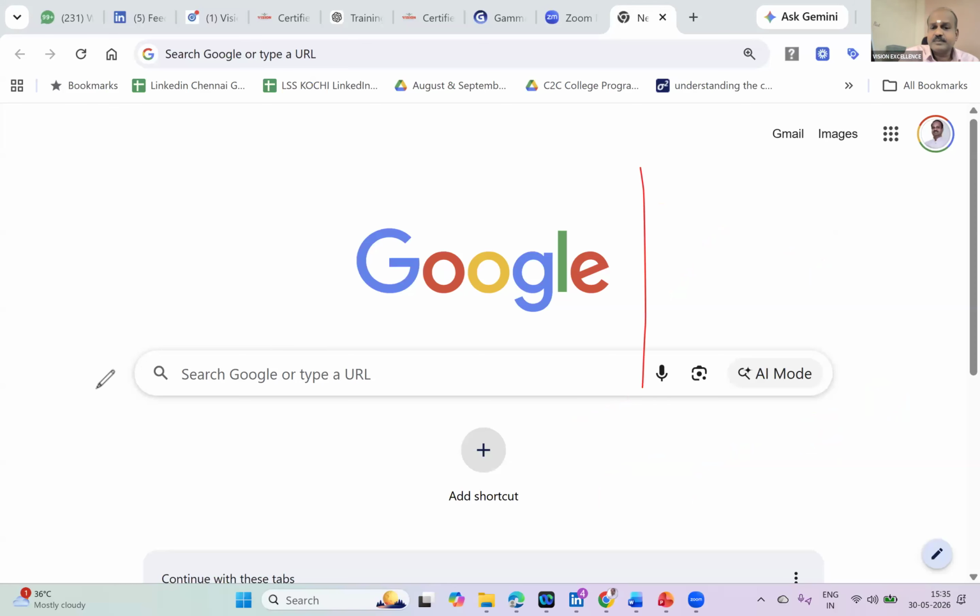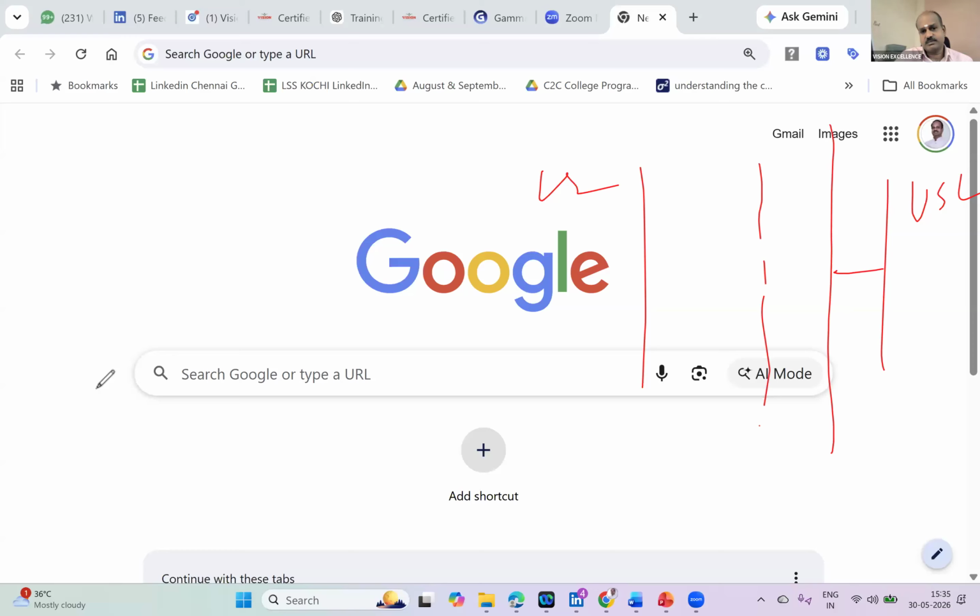So now, imagine your process is shifted. There is LSL, there is USL. Your X bar is supposed to be here, but actually it has come here. Now, how much tolerance do you still have? You only have a little. And this little area is called USL minus X bar. Do you understand, all of you?